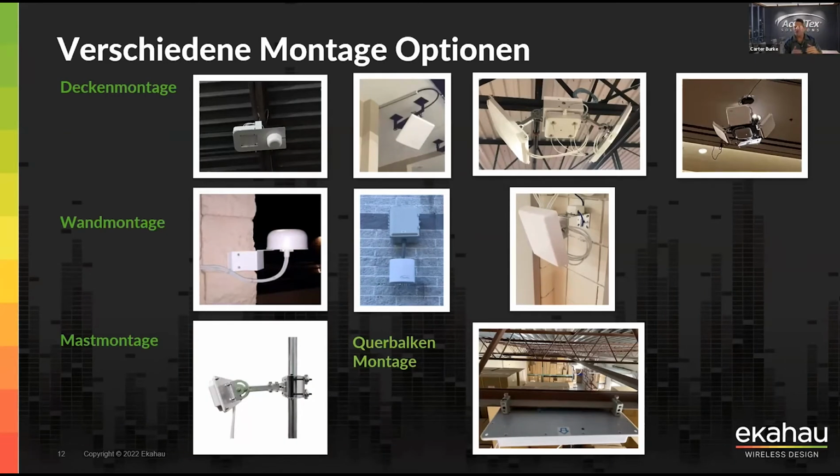But remember, you can go longer distances in focused areas. The more directional the antenna, the higher the gain, so great, you go further, but you're losing all that side coverage. Just make sure you take that into account in your design. Yeah, you're going to go further, but if you want to cover here and over here, you're probably going to have to have two different antennas, two different access points, or whatever.